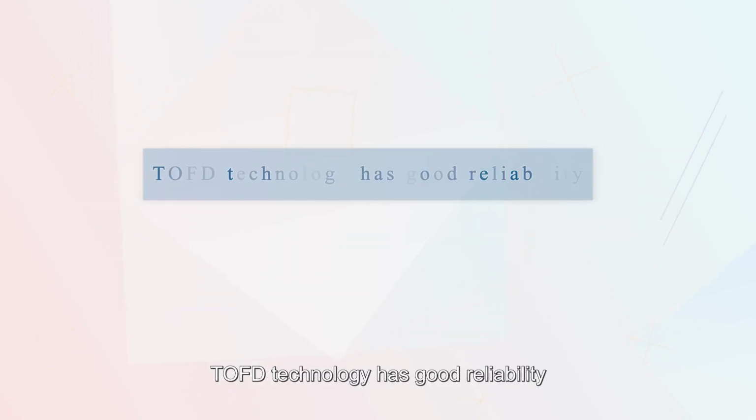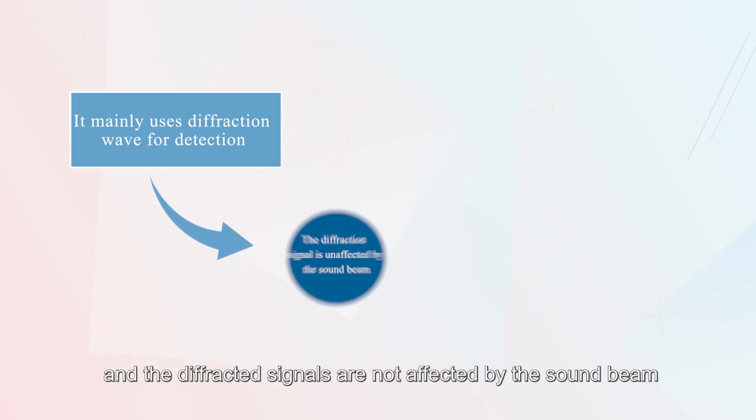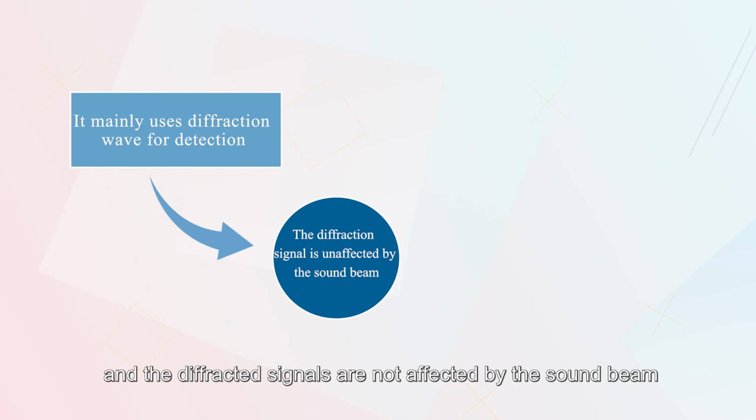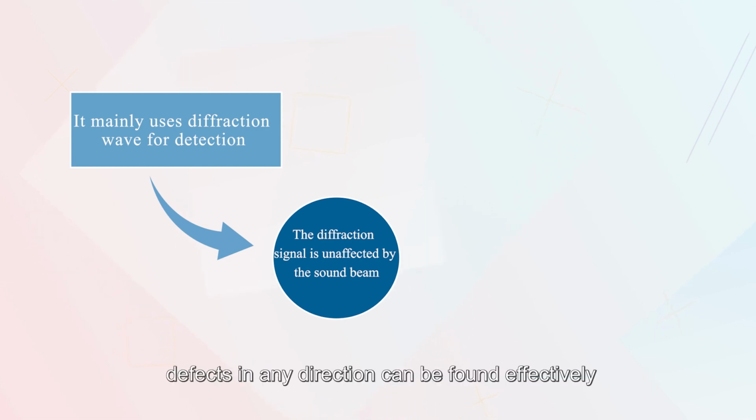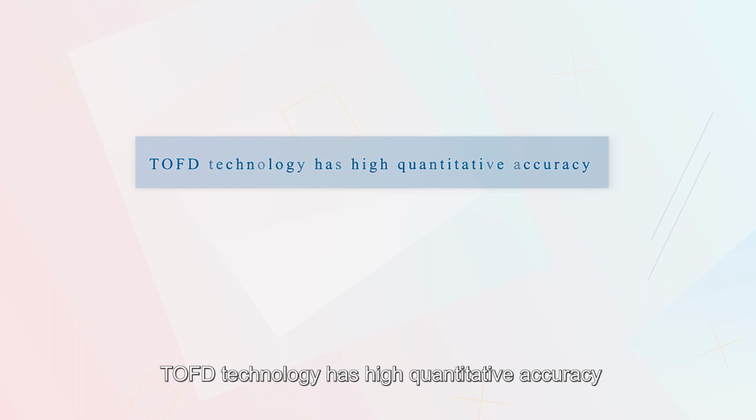1. TOFD technology has good reliability because it mainly uses diffracted waves for detection, and the diffracted signals are not affected by the sound beam. Defects in any direction can be found effectively, which gives this technology a high defect detection rate. 2. TOFD technology has high quantitative accuracy.